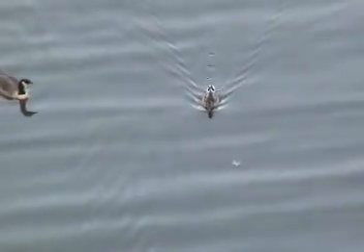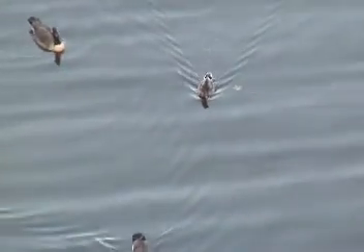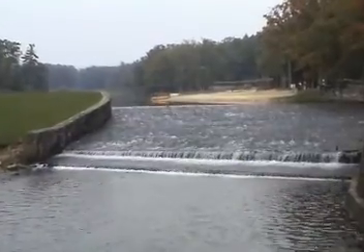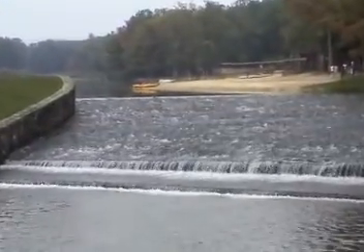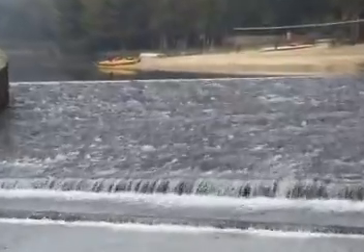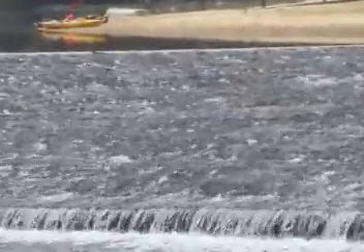There's a strong analogy between these liquid surface waves and shockwave phenomena in supersonic gas flow, where swept-back waves occur when the Mach number is greater than 1. The Froude number is also important in open channel flows, such as the spillway downstream of a dam.